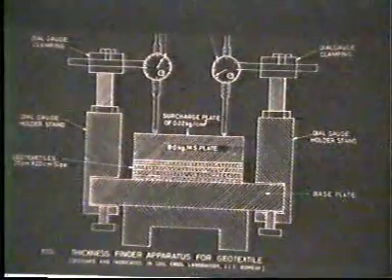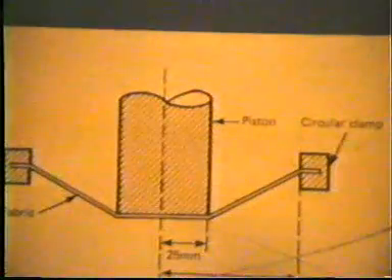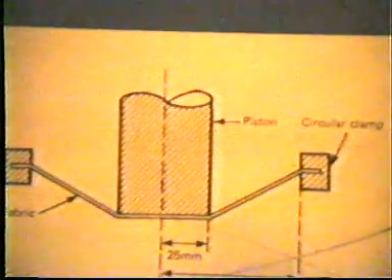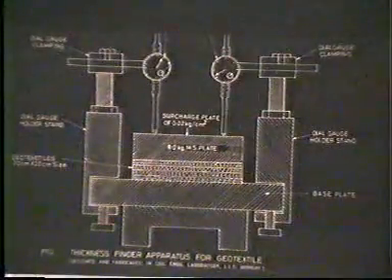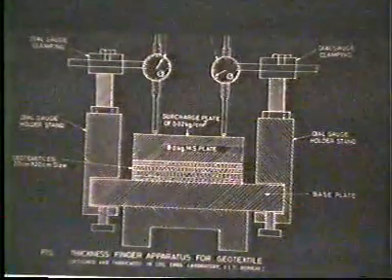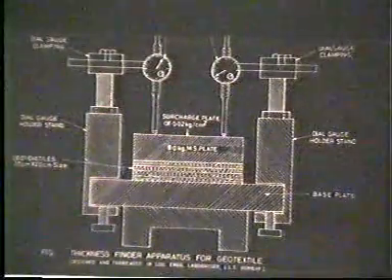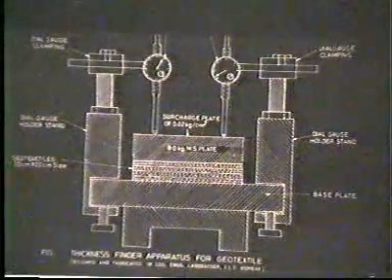Now the thickness is measured as the distance perpendicular to the fabric's plane between the upper and lower surfaces of the geotextile, measured at a specified pressure.